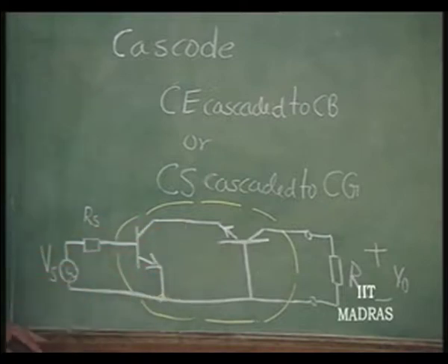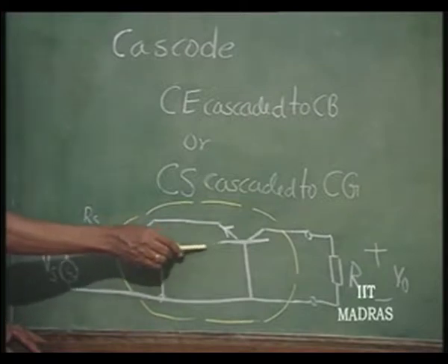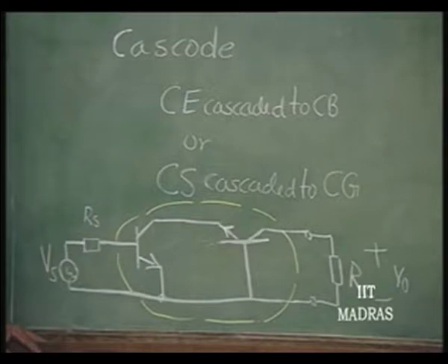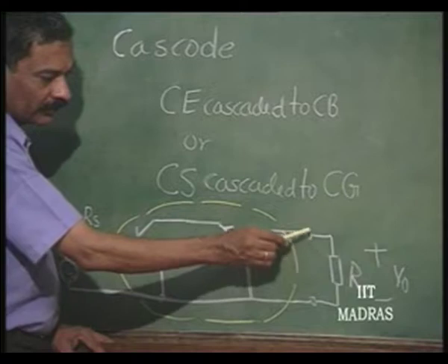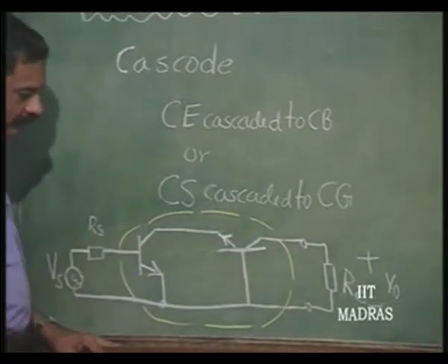Intermediate time constant is caused by the output resistance and input resistance in parallel and the capacitance at this junction. And this time constant is caused by the load, the output capacitor and the output resistance of the structure.